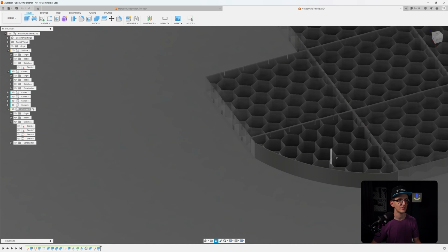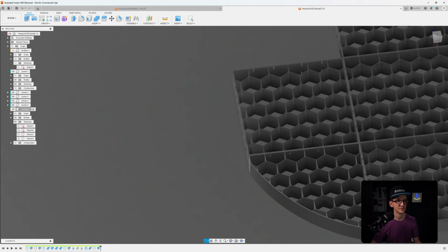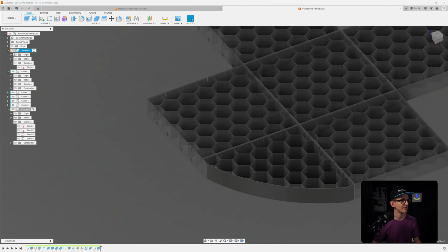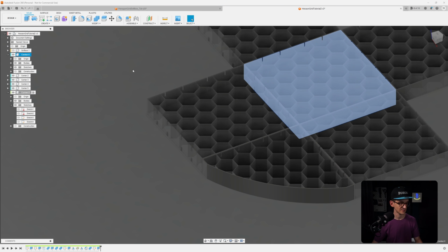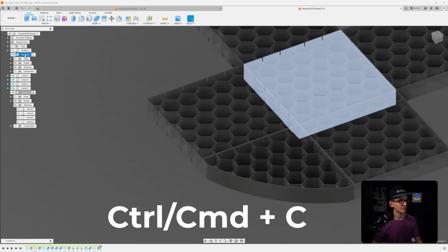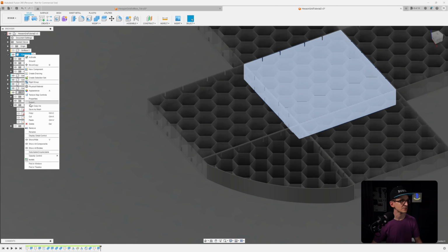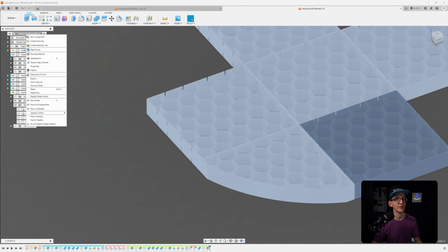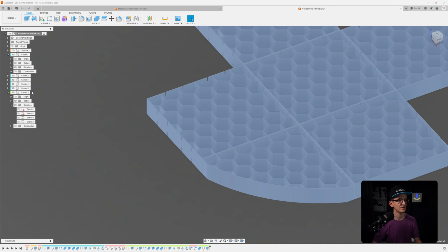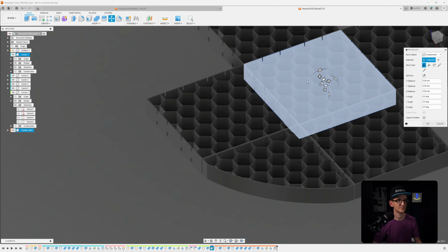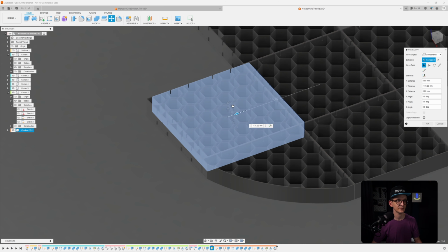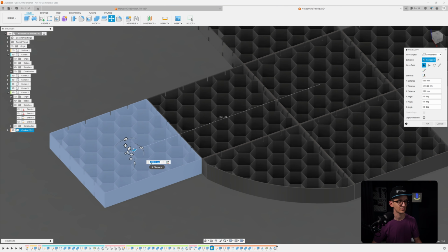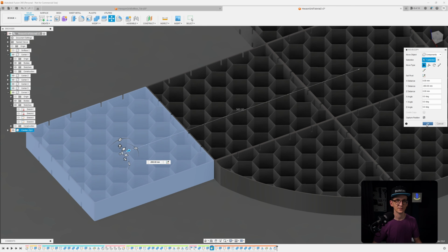And we do the same now for the, let's call it the edge component, the edge part. And for that, again, we copy paste, sorry, not the softbox, we copy paste a center. So we hit Control or Command C, or actually copy, and then select the general top level component, and say paste new. And now we can move this in place, so 18 centimeters in this direction again, and then further 18 centimeters, which goes all the way to 36. And we capture position and hit OK.